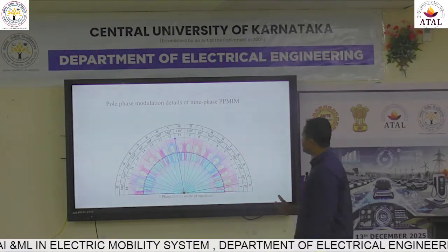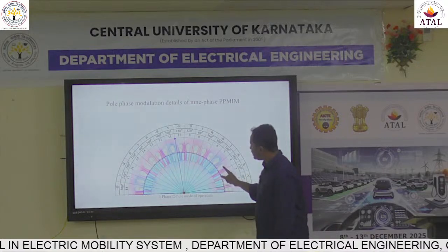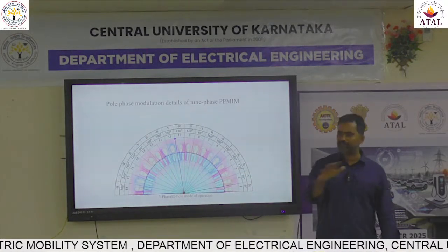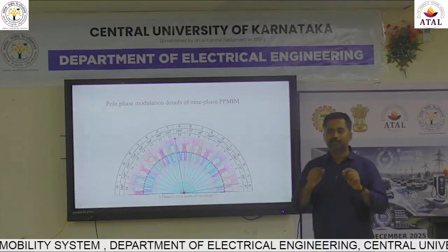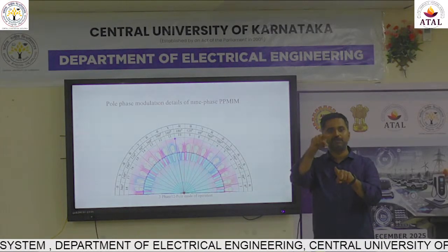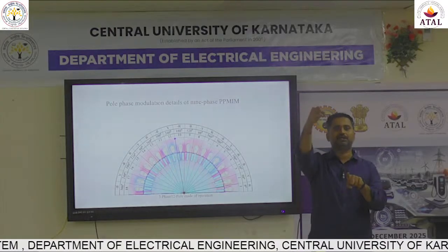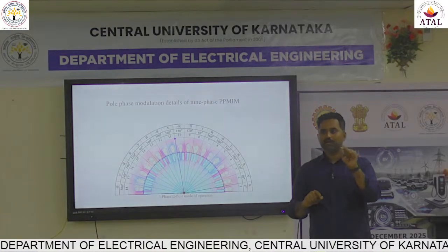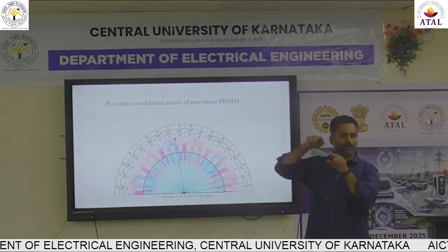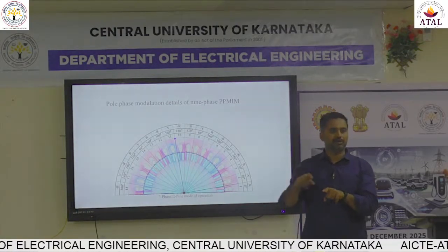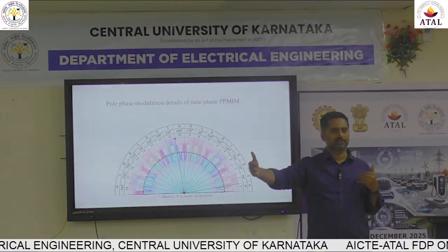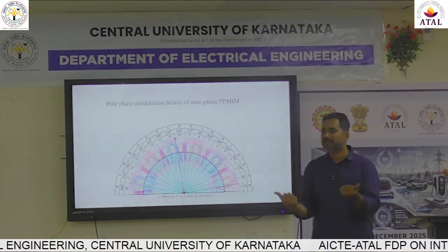And on top of it, these conductors, we always assume the top and bottom conductors. I strongly believe that some of you could have done this. The leakage flux of your windings will depend on the placement of the conductor, whether inside or on the top side. In the induction motor with deep bar systems, we could replace one bottom conductor and one top conductor. That kind of luxury we may not have here because the number of phases is increasing. So how do you handle that leakage inductance?